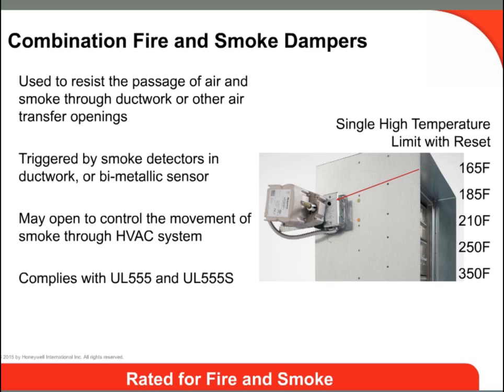When these actuators are used in smoke damper applications, they're usually controlled by smoke detectors or fire alarms. Often they are wired to a fire control system where they can be remotely operated as well. Like single-purpose dampers, they may be manufactured for static or dynamic systems, and they may be round or rectangular. The actuator may be electric or pneumatic and must be installed onto the damper by the manufacturer, where the entire unit is tested to pass the UL tests. Field replacement of the actuator is permitted with a like-for-like replacement or a technically superior one.